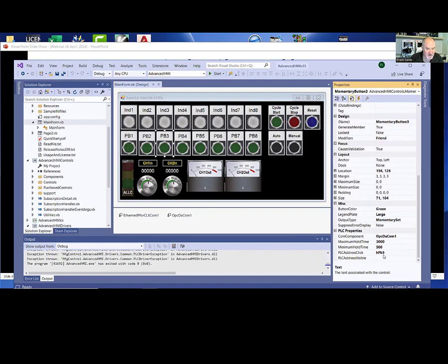And the tag is HPB3. So on my other HMI I'm working on, it is HPB.3, right? Actually, this would be HPB.2 because it's 0.1.2. So that's a little confusing for students. So I would have them, for instance, alias a new tag and just call it PB1, alias it to HPB0. So you understand the idea behind that.